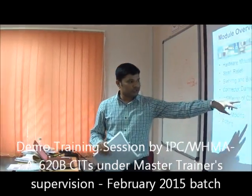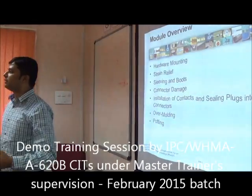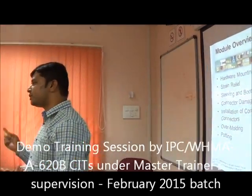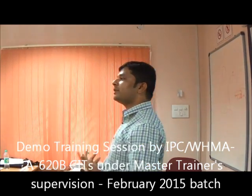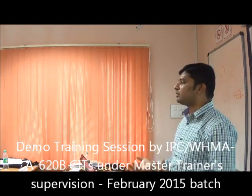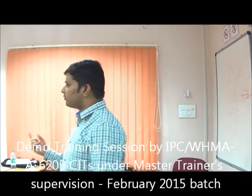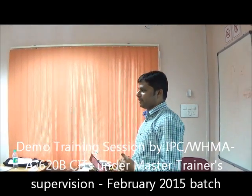And then installation of contacts and seal plugs. If you have a 50-pin connector, maybe the actual termination will be using 30 pins. The remaining 20 pins have to be installed with seal plugs, dummy contacts. Maybe it depends upon the customer. Some customers may ask you to install the dummy contacts as well as seal plugs. Some customers may ask you to just install the seal plugs.